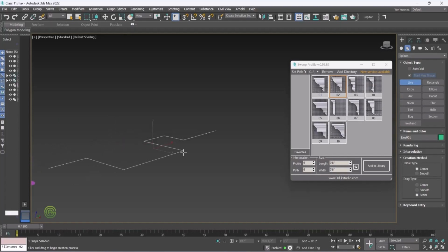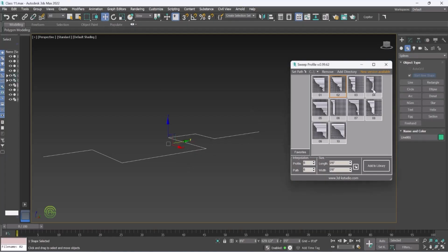Like this, if you have an exterior profile, exterior facade. Now, if you want to give a classical architecture style, just go to profile and click on 4. See, once I clicked on 4, this 4th option is applied here.